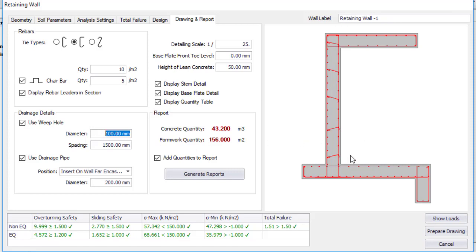What about draining water in this other direction? I mean the direction that is facing me. Okay, so you can use a drainage pipe in that kind of sense. The size of that drainage pipe, you can use 200 mm. So that is the default, but you can change it. I don't want to change that, but I'm just trying to explain why it is there.